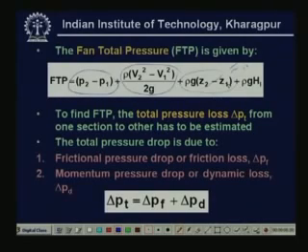So basically we have to deal with the change in velocity pressure, the change in static pressure, and finally the head loss, the pressure loss due to friction and other factors. If in the duct the inlet static pressure is the same as the outlet static pressure, then this becomes 0 because P2 is equal to P1. If you are using a uniform cross-section duct, then V1 will be equal to V2. If air behaves as an incompressible fluid, then this factor also becomes 0.